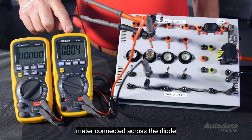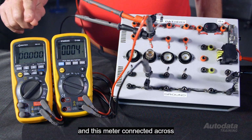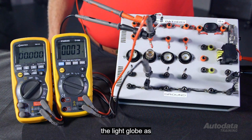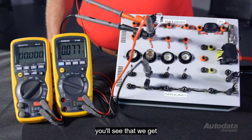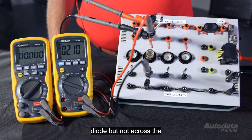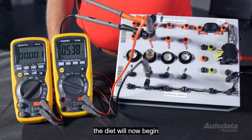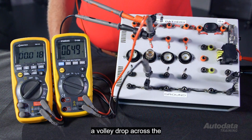I have this meter connected across the diode and this meter connected across the light globe. As I increase the voltage, you'll see that we get a voltage drop across the diode, but not across the light globe, until we reach about half a volt. The diode will now begin to conduct and we get a voltage drop across the light globe.